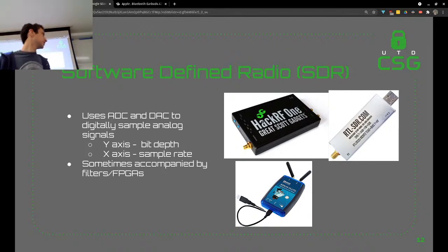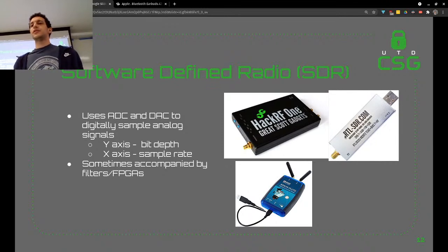These are just 3 of, I think, the most common software-defined radios. This RTL SDR is based off of a TV tuner, and they're like $24 on eBay or Amazon. It does receive only, and not a huge range, but it'll cover a lot of the spectrum, enough for you to play around with.